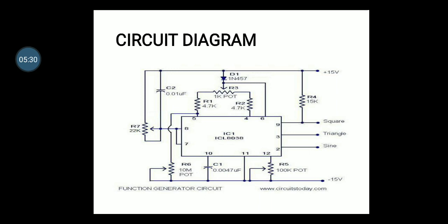As a result, we get a square wave at the output of the flip-flop and a triangular wave across the capacitor. The triangular wave is then passed through the on-chip wave shaper to generate the sine wave. To allow automatic frequency control, currents IA and IB are made programmable through an external control voltage.